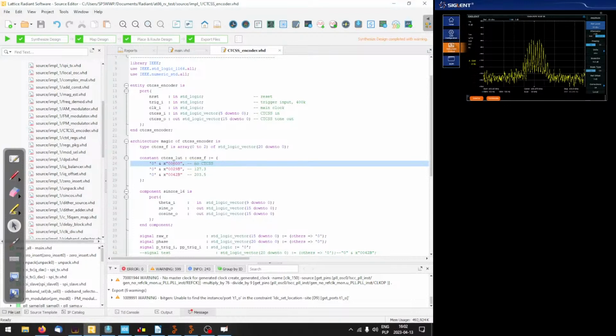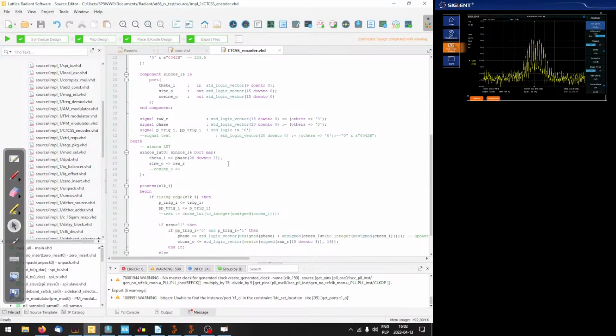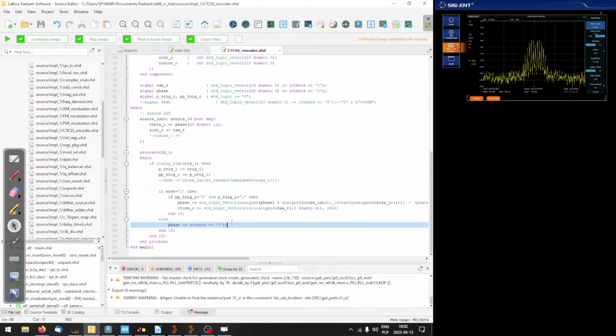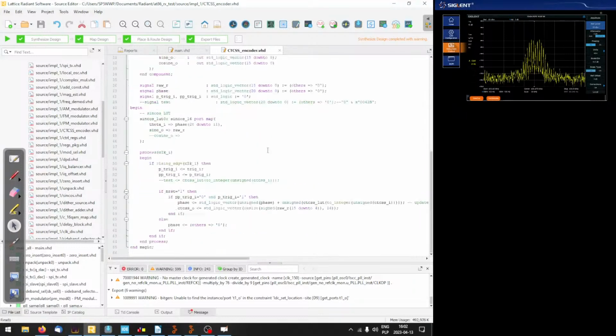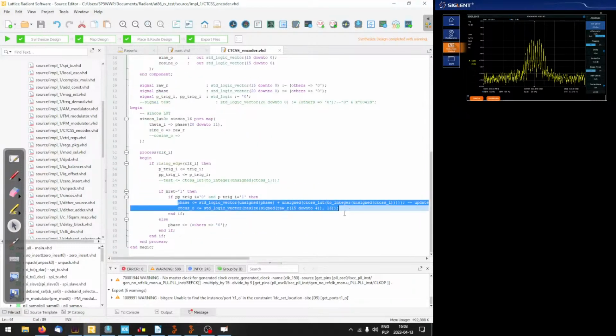And we have picked this one just by accident. So you can either set this value to 0 and expect the lookup table just to output zeros. So that's nothing. Or somewhere in the code, somewhere here, check if the input code for the CTCSS is 0, then don't perform any of this.